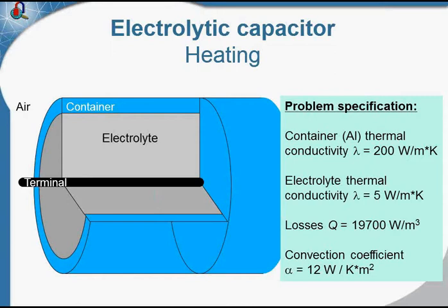I know the electrolyte thermal conductivity. It's 5, and I know the aluminum container thermal conductivity. It's 200. And the capacitor is cooled the natural way by the air flowing outside. I know the convection coefficient, it's 12. We know the losses, we know the material properties.